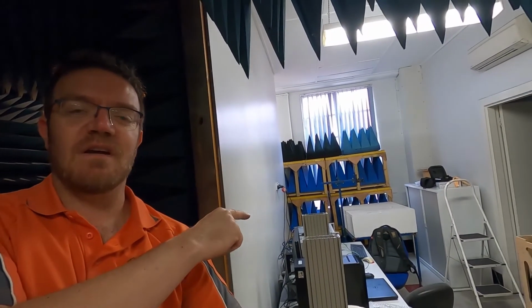So we all talk the same language, because if you want to only test antennas in a real-life environment, there's so many variables. So basically in a chamber like this, you take out all the noise, all the variables, you just have a clean setup where you take that VNA that I showed there. So that's the vector network analyzer. It sends something, you see how much it picks up, that gets you a complete picture.